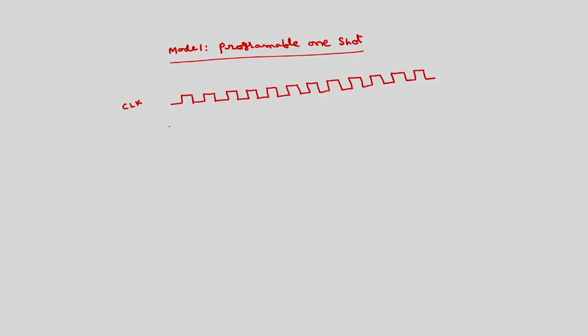Then here also this write bar signal has to be made low to load the count. Say n is equal to 4. For explanation purposes I am taking smaller values here. Otherwise this can be a 16 bit count, varying from 0000H to FFFFH.